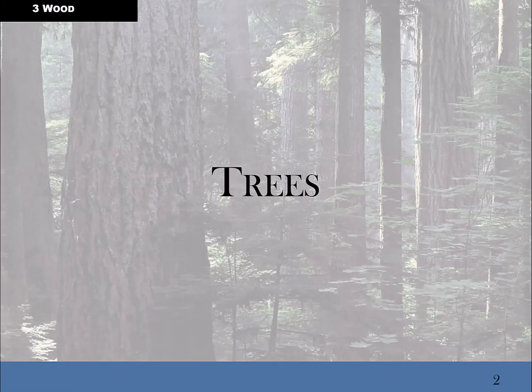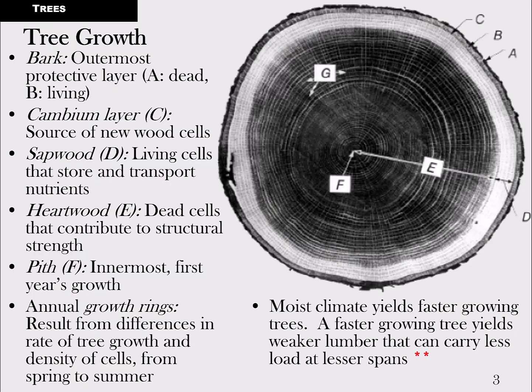So yes, we're looking at trees themselves, of course, but if you look at this log here, in this another section like this, there's a bunch of terms here, and they're all kind of interesting. What I really care about you understanding is the concept of these annular growth rings result from differences in the rate of tree growth throughout the year, and you get a more dense density, a tighter density of wood in the dark rings. That wood is stronger or tougher to drill through or cut through than the pulpy material that grows when it's growing fast in the spring.